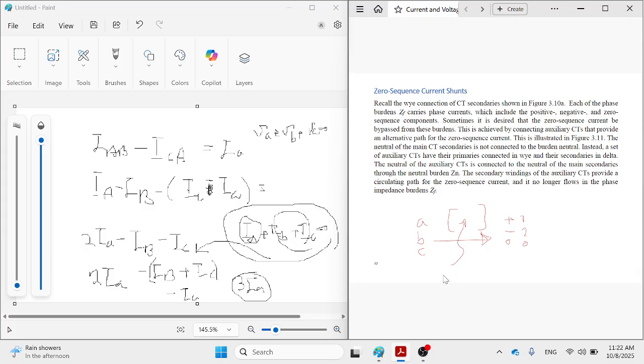Okay, Fortescue matrix. This one will be reviewed in chapter 4, here, and then later in the power system operation and control unit. You will review it to calculate the fault in the same way. Okay, so this one, the Fortescue matrix, is usually used for the unbalanced fault, of which we have different types of fault. Okay, if you review chapter 1 you will see.